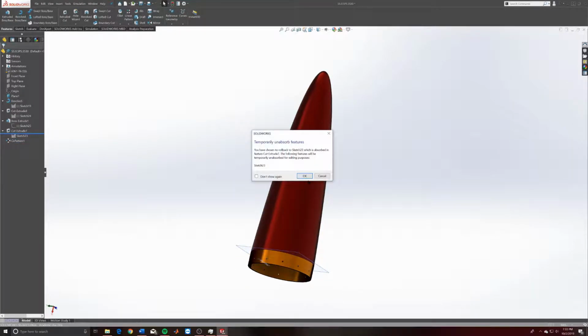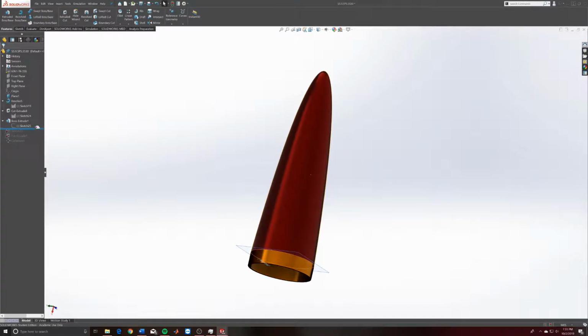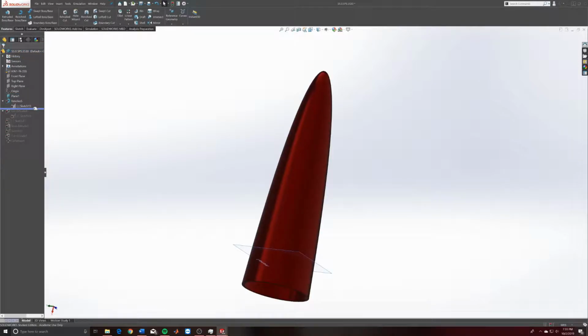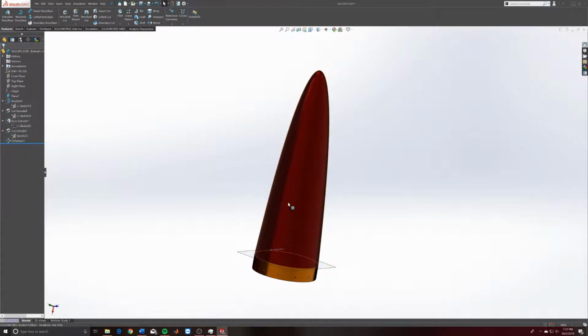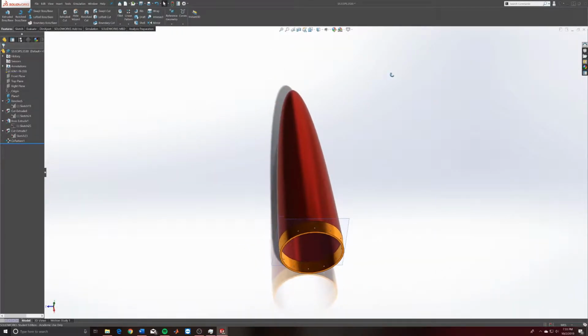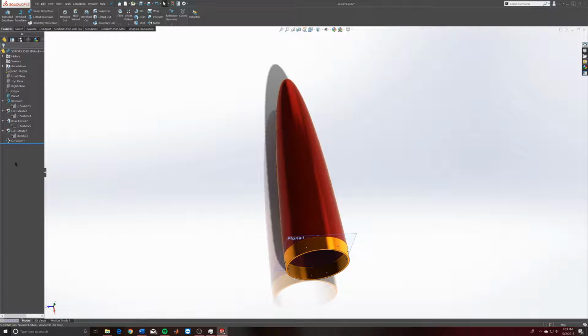You can scroll up and roll back features to see what your part was before you did that step. When you start a build, it'll be plain, and then as you add sketches and parts, you can roll back between the two. You can go in there and edit sketches at any point, and you can modify each individual part without affecting later steps. But that's if you design it correctly. That's just parametric drawing.